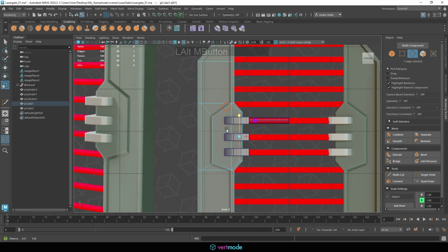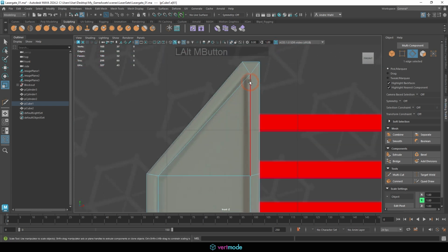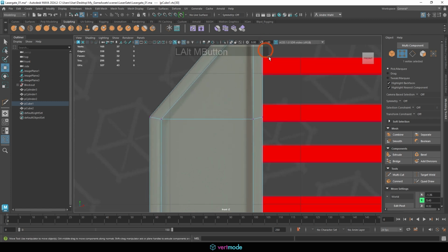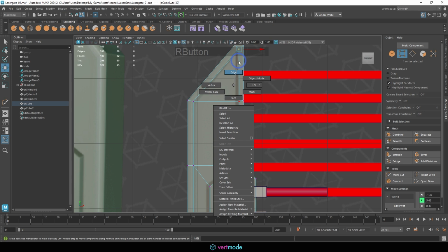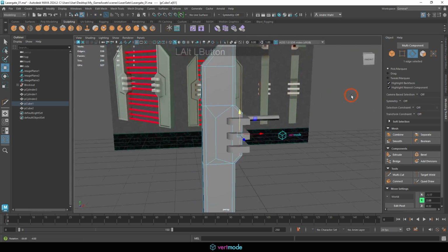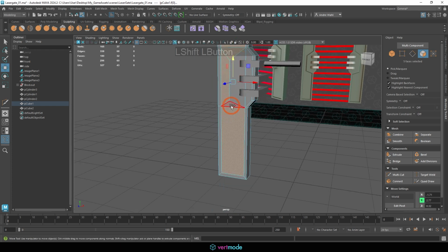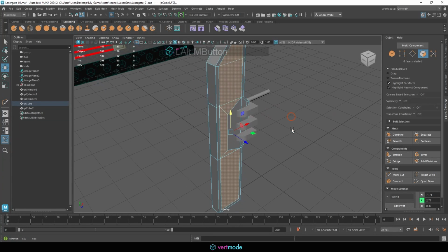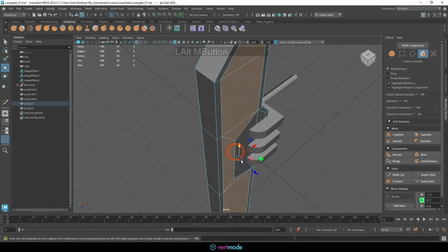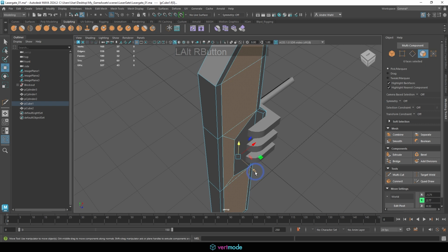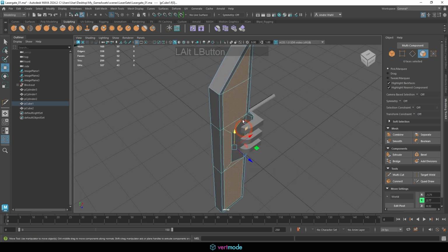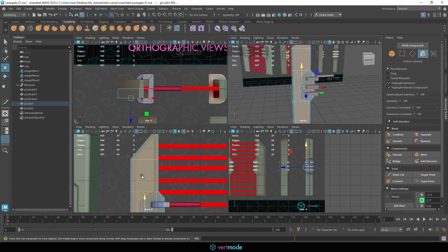So with that in place, we're pretty much good to go in terms of extruding this. The only thing I might want to play around with is areas like this that seem to be a little bit off here. I could put this exactly here, but I think that's like a smoothing artifact, so I'm going to keep this where it is if possible. And ours may be more or less precise than our reference. But with all of those in place, what I can do now is come into here and select these faces, and we can extrude these down to get that inner area. Now, a quick way to extrude, like I mentioned in a previous video, is just taking what we have here, and we can push in with this with Shift, but I might want to push in and scale this in to create that sort of offset we see here.